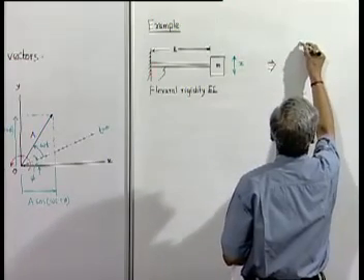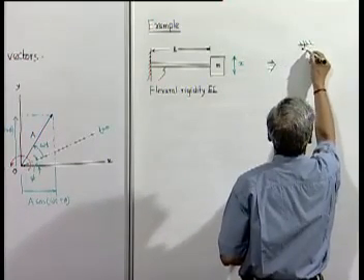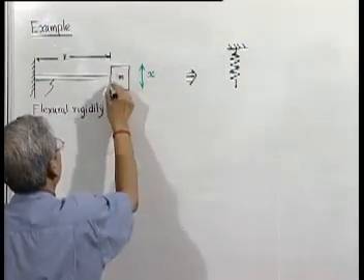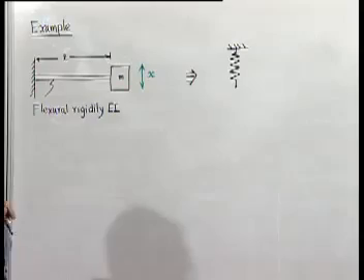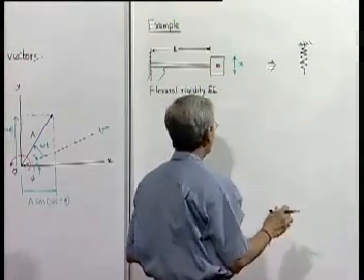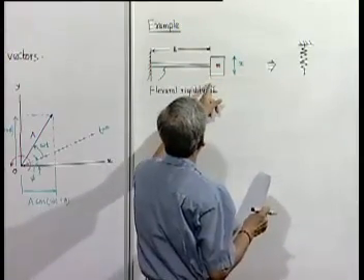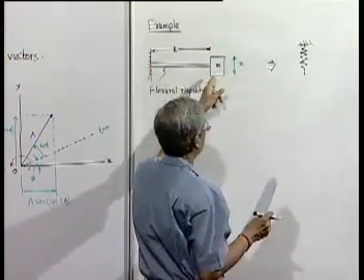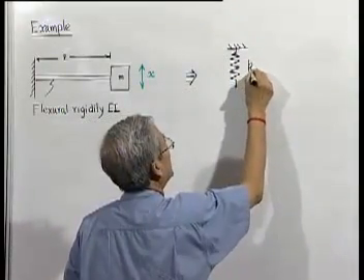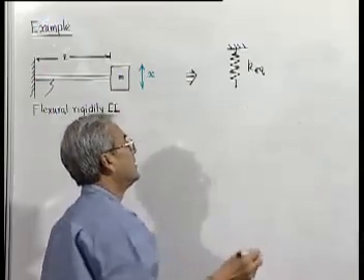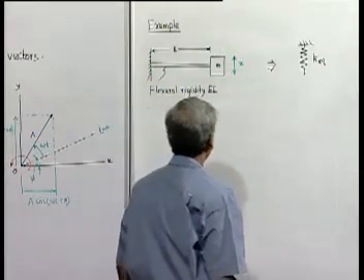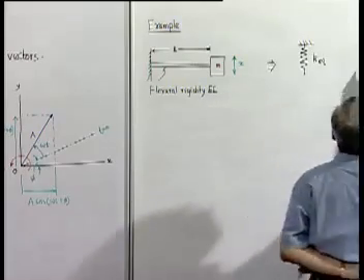We can make the cantilever beam's end, which can move up and down, subject to some constraint force which is proportional to the deflection and multiplied by the stiffness. So, therefore, we can represent it by the equivalent spring, a massless spring, whose stiffness is simply K equivalent. How much is K equivalent? How to find it out?